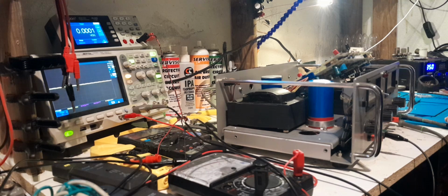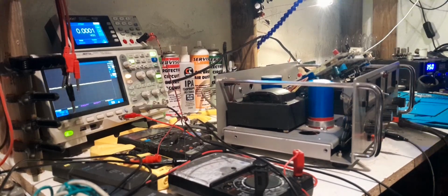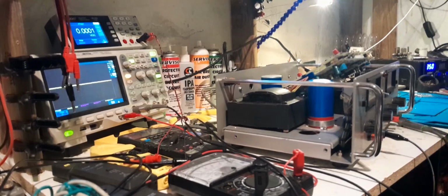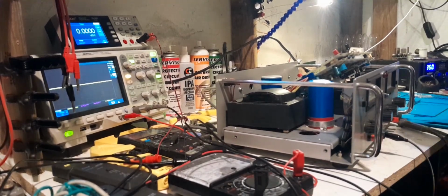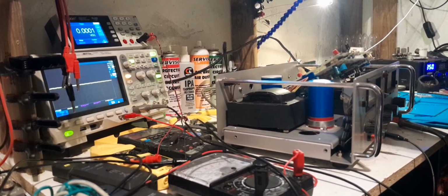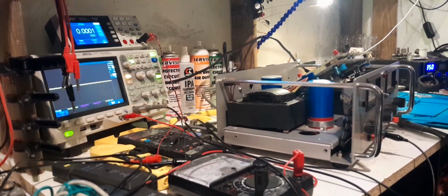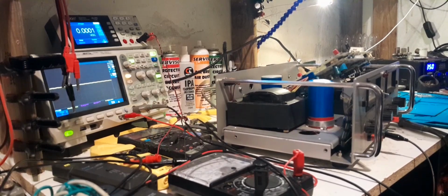So you've really got to think about what part of the circuit you're looking at as to exactly how you're going to hook up your ground probe. I can already tell you the thing that's really been hard for me with this supply is even just grounding to power rails and the output. I've run into problems where I'm getting inconsistent measurements. So let me think of a good example of this.